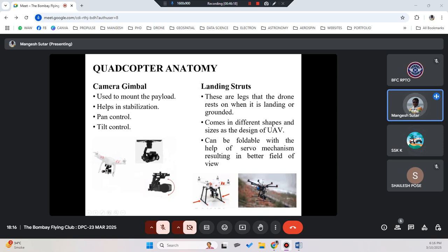And the gimbal will also sense, since the gimbal is fed inputs through the IMU also. So it will help in stabilization. So my pictures will be very stable, without blur or vibration in those pictures. So the gimbal actually helps you to have a stabilized camera for motion when you are capturing images or videos.